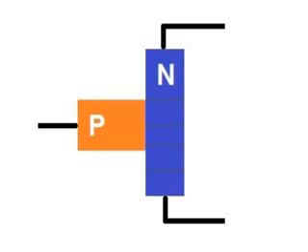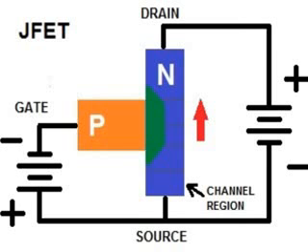Here's another interesting aspect of the field effect transistor. When the FET's gate is reverse biased, there is a depletion region between the N material and the P material. The depletion region is an insulator, and it's between two semiconductor regions, each of which conduct electricity on their own. So what's another name for two conductors with an insulator between? Well, that would be a capacitor.